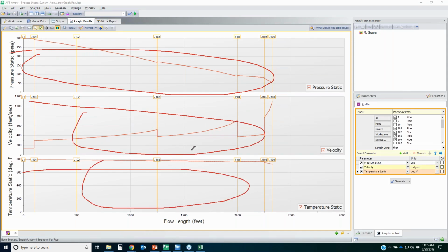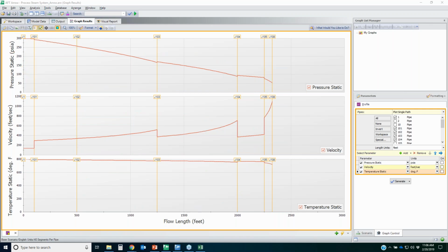And so if this is the type of system that you're working with, then your answer's in Arrow. You could bring this model into Fathom and model it, and you're just going to see how Fathom is just dead wrong for this type of system. So it all depends on what your system is and how high of velocities you can get until incompressible flow methods are no longer good enough. You're always going to be uncertain. That's the key thing to take away here.